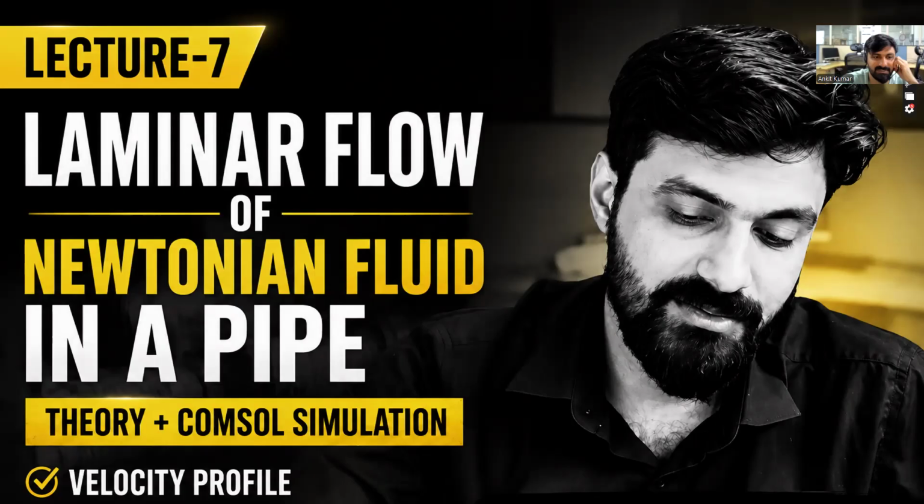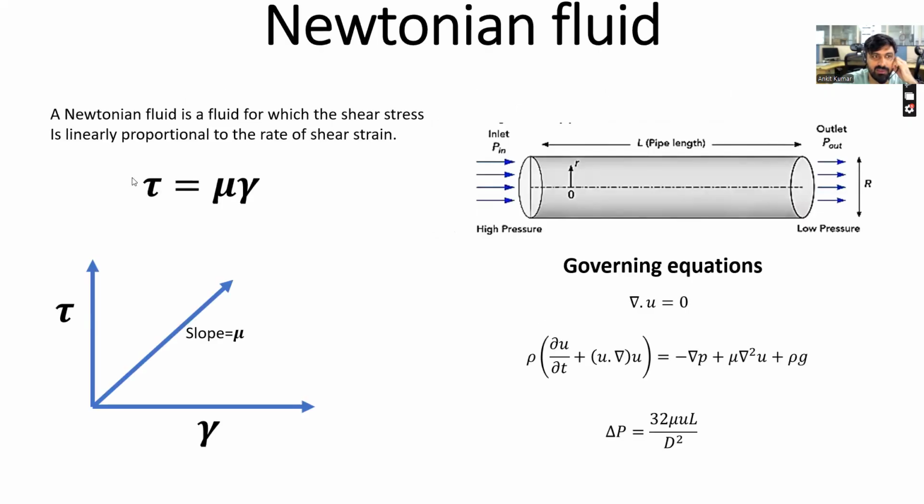So to understand these things, first we should know what Newtonian fluids are. When we talk about the Newtonian fluid, the governing equation is Newton's law of viscosity, which is tau equals mu into gamma dot, where tau is the shear stress, gamma dot is the shear rate, that is del u by del y, and mu is the viscosity. If we plot the shear stress versus shear rate, where shear stress is on the y-axis and shear rate is on the x-axis, the slope of this line gives you the viscosity.